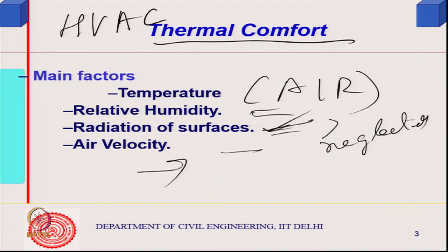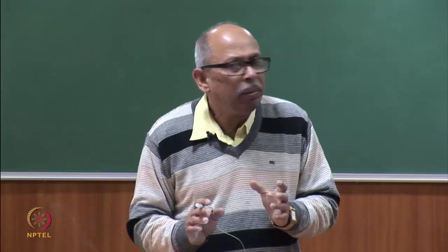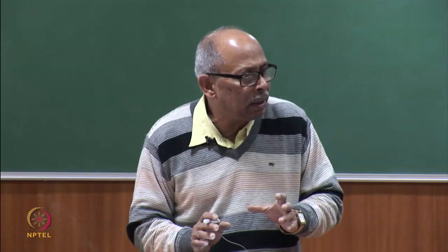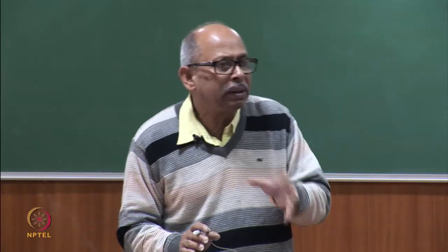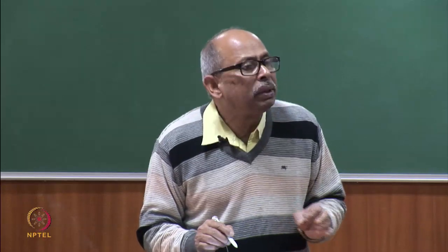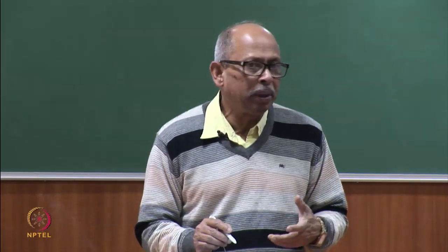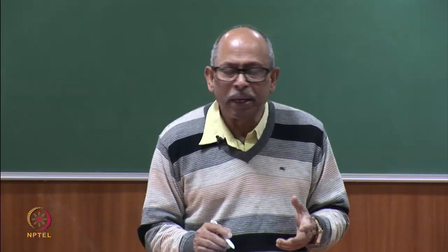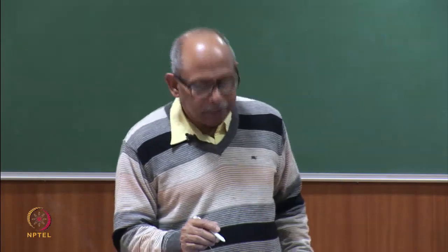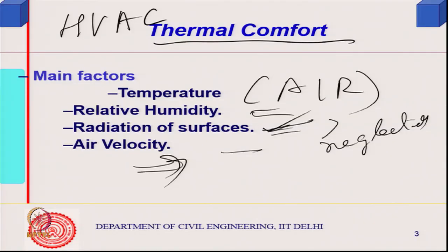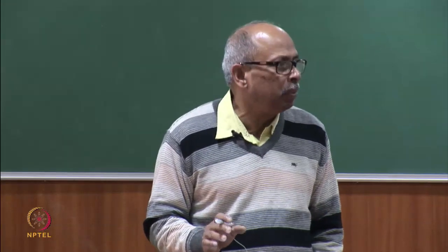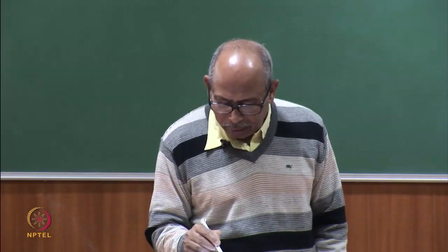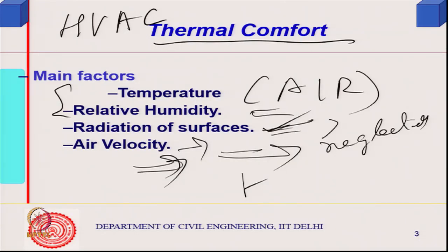and usually it is a closed room. So, there will be little natural ventilation. Leakages and infiltration could be there, but that is taken care of. So, air velocity per se is not there to do convective cooling, significant air velocity is not there. It is by and large still air, closed from all sides, and we normally do not operate fans etc., if the HVAC is working properly. So, this is also not needed. So, what we try to control is these two, temperature, a comfortable range of temperature, and generally this is our